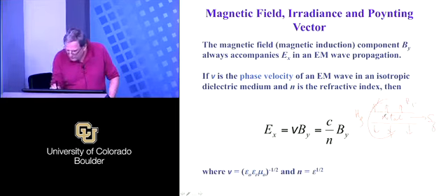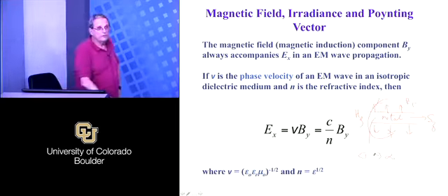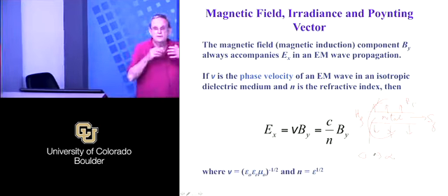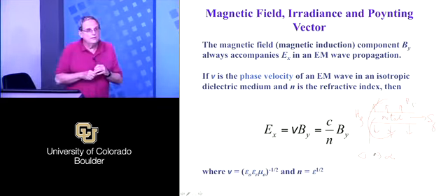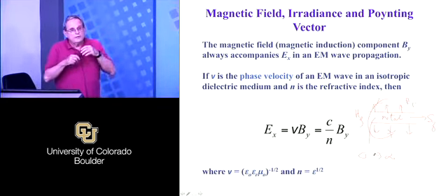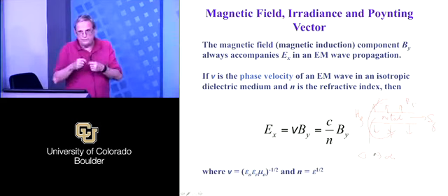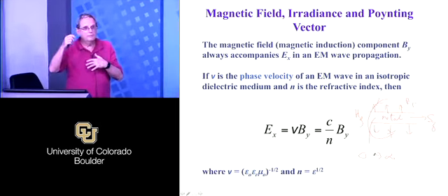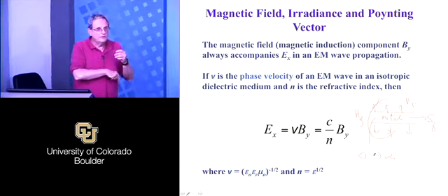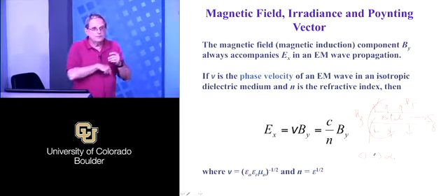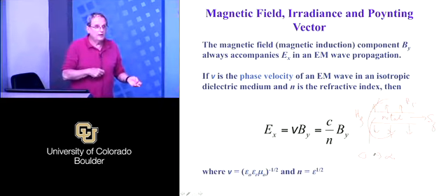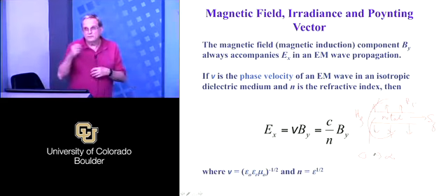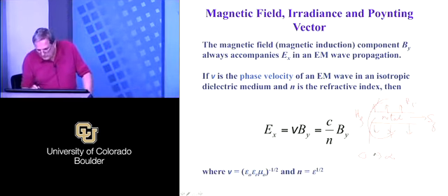So he said, well, look, in the metal, the conductivity is high, at least at RF frequencies. As most of you probably are aware, the epsilon, the imaginary part of it, is very large at RF frequencies. It's actually quite negative at optical frequencies. Metals don't conduct at optical frequencies. They're plasmonic rather than conducting. Only at radio frequencies is metal conductive.